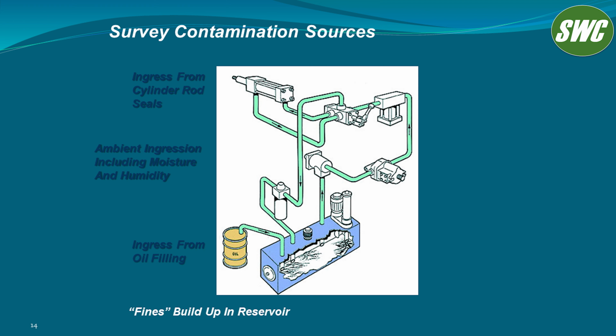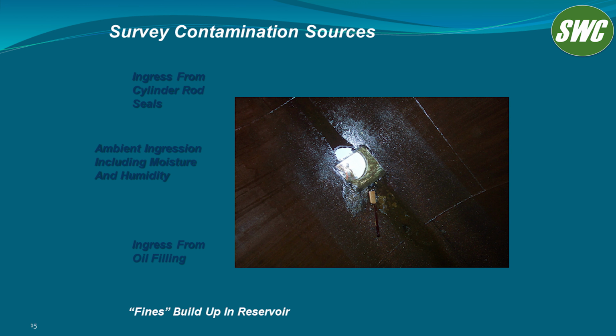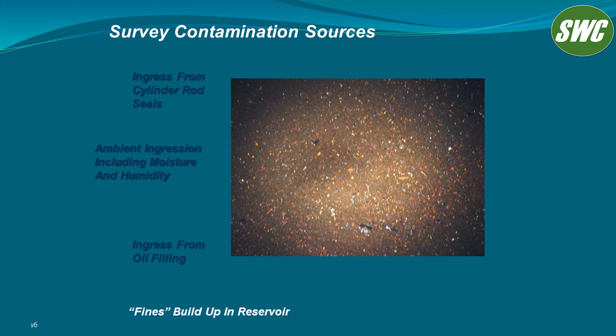Reservoirs are built to settle out dirt, and over a period of time, you're going to have fines build up within the reservoir. On one troubleshooting escapade, I went all the way to Chile to discover such a fines buildup in a reservoir that the major oil company couldn't find. They said they had cleaned the reservoir recently, but after we started seeing fines in the oil analysis, and then we opened up the tank, we found there were considerable fines in the bottom of the tank.